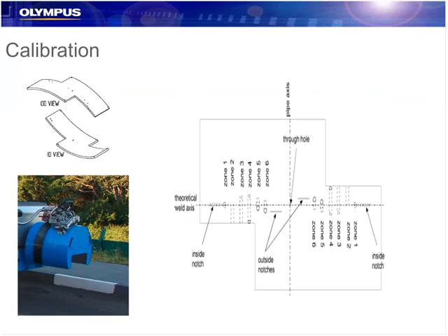So here's a typical calibration block shown here for onshore mainly. We use what we call a Z block. So to reduce the weight of it, we basically have a Z-shaped block. One side is basically upstream, downstream. And we'll place this in a dummy pipe often to reduce the weight because depending on the thickness, the block could be very heavy.